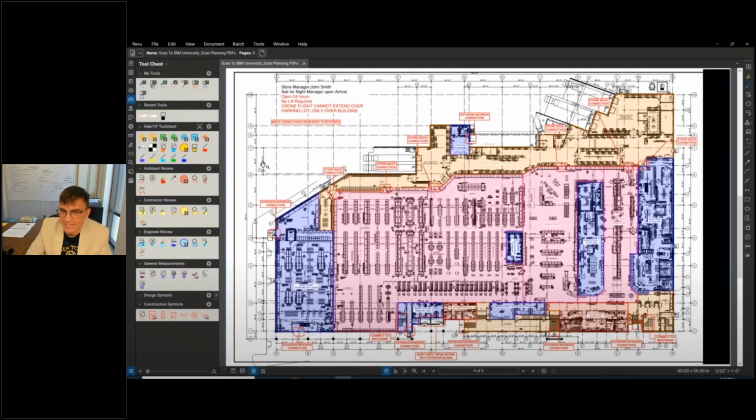On your scan plan, identify critical tie locations, the areas where it's really important to get good overlap, the one door where it's the only access from an entire side of a building to the other entire side of the building, where if you don't collect good scan data at that doorway, nothing works. And highlight these areas and make sure to do a good job scanning in those areas.